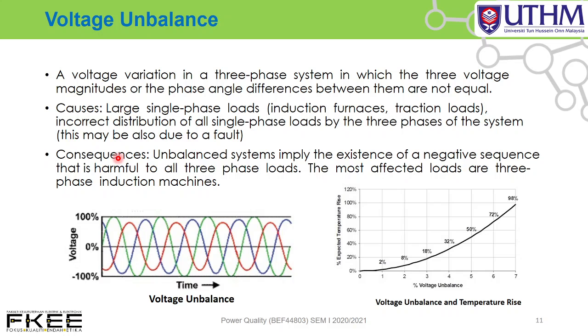What is the effect of the voltage unbalance? An unbalanced system implies the existence of a negative sequence, which is harmful to all three-phase loads. The most affected loads are three-phase induction machines. This is one of the effects of the voltage unbalance.